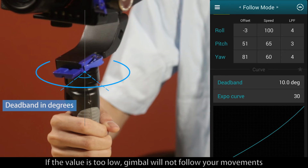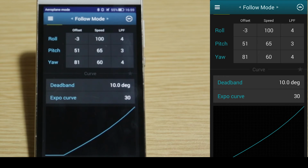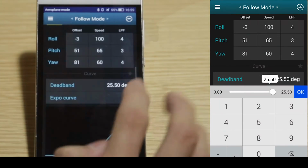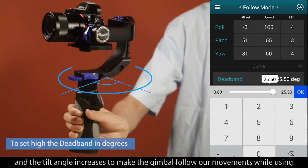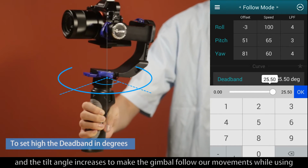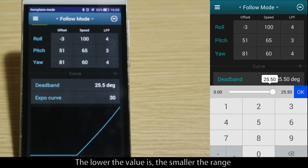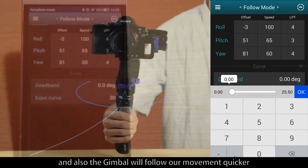If the value is too low, the gimbal will not follow your movements. The higher the value is, the bigger the range, and the tilt angle increases to make the gimbal follow your movements while using. The lower the value is, the smaller the range, and also the gimbal will follow your movement quicker.